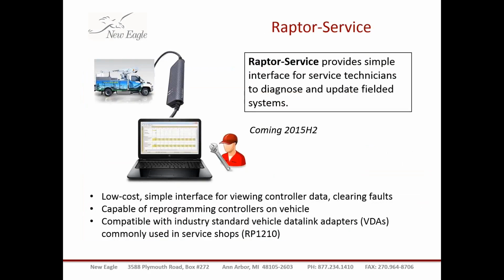This is a new product that's coming later in the year. Raptor Service provides a simple interface for service technicians to diagnose and update fielded systems. It's a low-cost, simple interface for viewing controller data. You can clear faults. You can create your own screens. It allows a service technician to reprogram the controllers within a vehicle, compatible with RP1210 tools. It's a nice low cost, simple service tool.